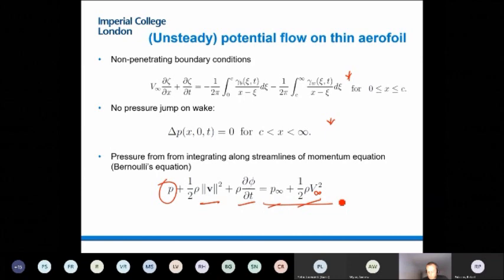We have this total pressure upstream, and as we go down the airfoil, that magnitude gets conserved. This is P infinity plus 1/2 rho v squared. And then anywhere on the airfoil that you go, you have a pressure which is proportional to how much the flow is accelerating. So what is the change of velocity? And indeed an acceleration term, which is how the velocity changes with time.